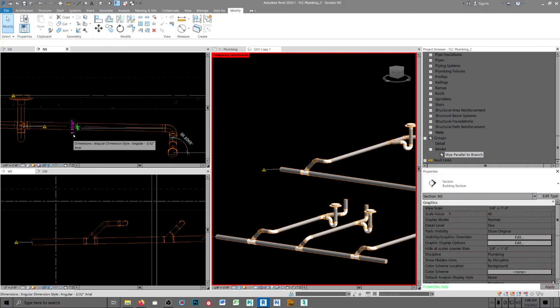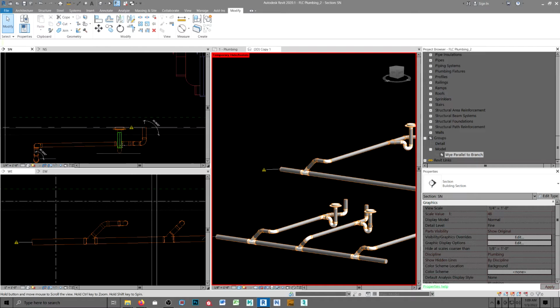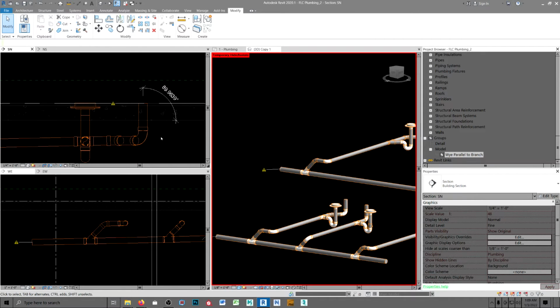And I highly recommend going in and changing your settings to 4 decimal places if you want to have any success in connecting these sloped lines. Revit doesn't always give you the right answer, and that's really not the issue.